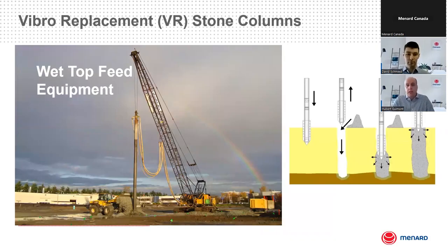Basically, in there, you're just driving the probe down to your targeted depth, and as you go up, you pour some stone from the top, and you build a column from the bottom, making sure that you put the energy, the vibration energy, into the column, and so you're building a system of stone columns doing that.